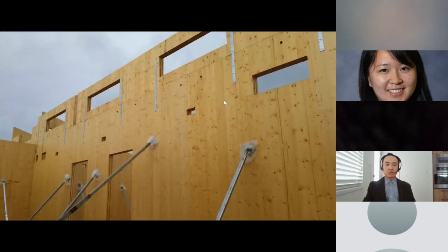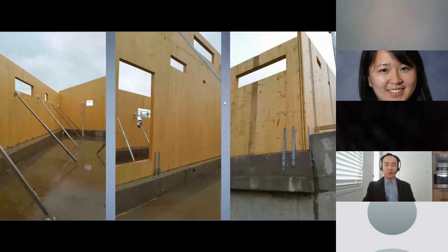And then this is the operations building during construction, showing the clear story windows. Those little wall piers between the windows had to be detailed with metal straps to take overturning forces into the lower part of the shear walls. And then more construction photos for the operations building, showing temporary strut bracing for the walls, as well as in the middle photo on the far right, you can see tension hold downs taking overturning forces into the concrete structure below.